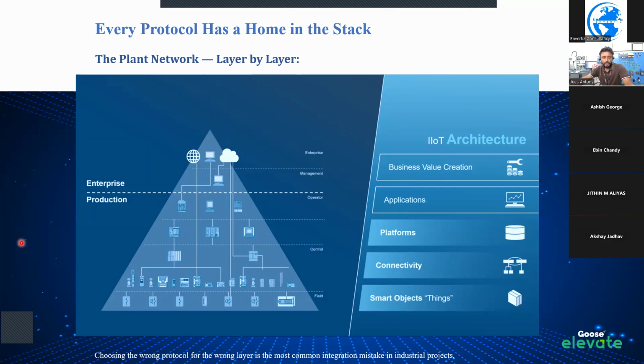The next level, we can have SCADA and HMIs, which is where operators interact with the machine. And above that, we can have business value creation layers like centralized SCADA, MES systems and ERP systems, which are used to create business value in the industry. And nowadays, all the communication protocols cannot communicate to the cloud system, so we have specially designed communication protocols to communicate with the cloud system. When it comes to cloud systems, we are taking the data from the factory to outside the factory, to systems like a centralized server and cloud hosted PCs. We will be giving that data to the cloud hosted PCs.